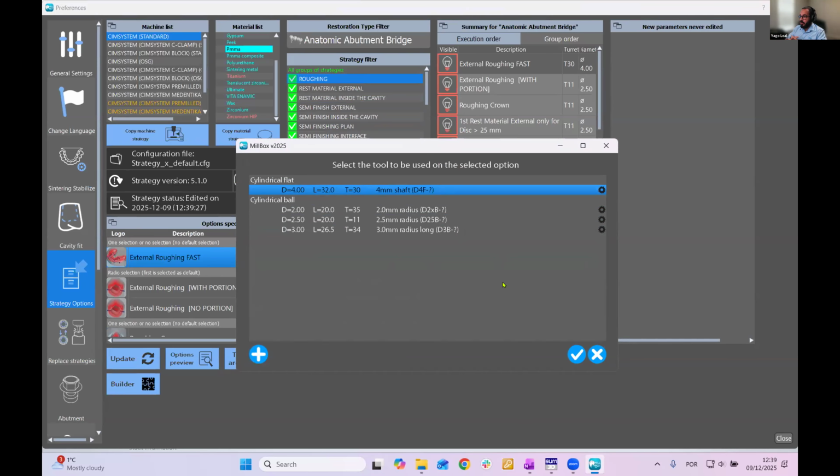For example, on the roughing, as you can see, we only have bigger tools assigned that are capable of producing the roughing toolpath, okay? Usually we don't set the 0.6 to rough because it would take hours to remove all that material, right? So depending on the operation you're trying to assign a tool to, you won't see every tool that you have available, okay?